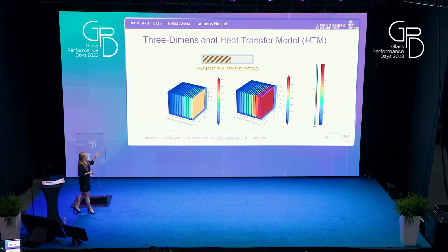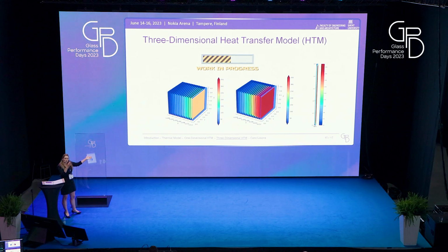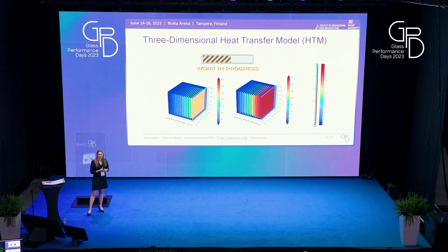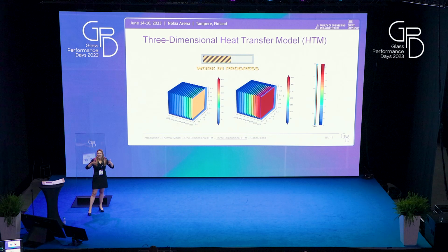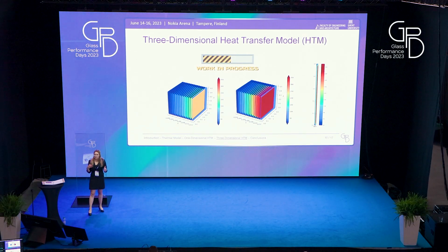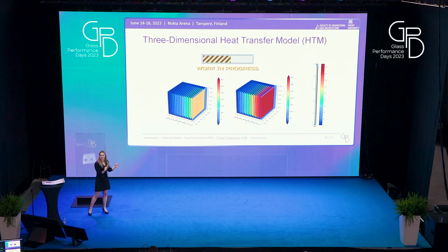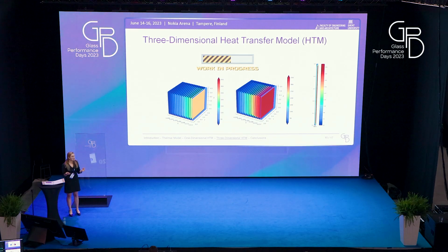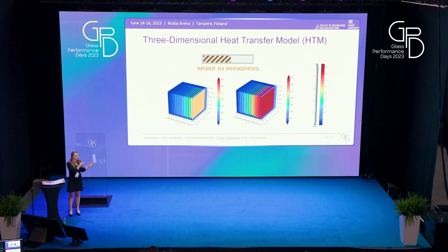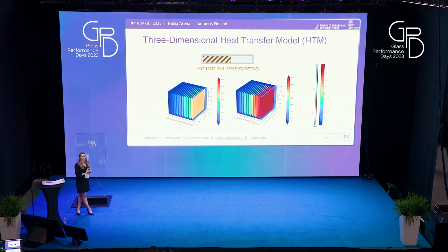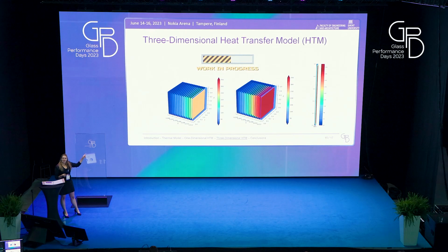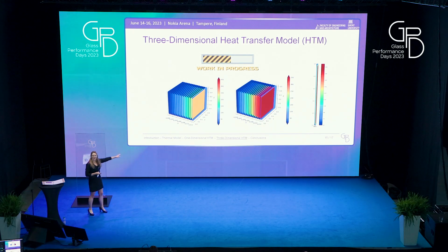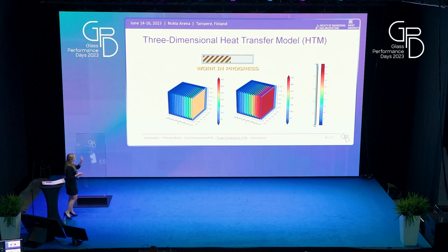The main reason why we do this is that now you have heat coming from one surface, but when we talk about structural glass, which is also something that Maximilian showed, when you have a beam, for example, you have heat coming from 3 sides. A lot of thermal models don't give you the freedom to model these boundary conditions in detail. If we have a 3-dimensional model that we control totally by ourselves, we can implement this. So that's the aim of this 3-dimensional model that we are working on now. We will also validate this with the experiments that we will do in the summer. But still, this is not final, so the figures are not yet validated. Just keep that in mind.